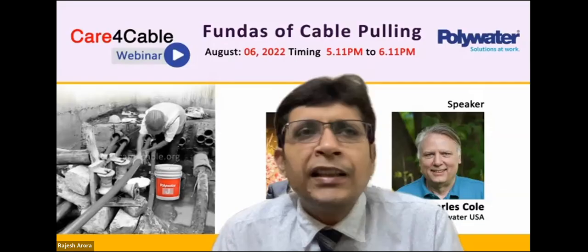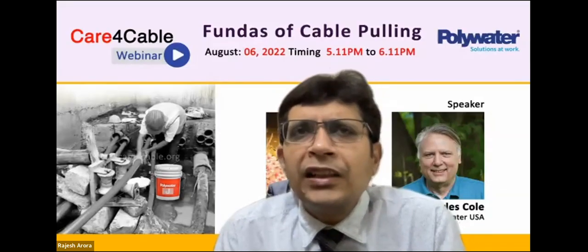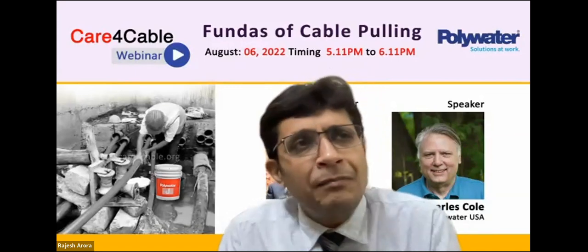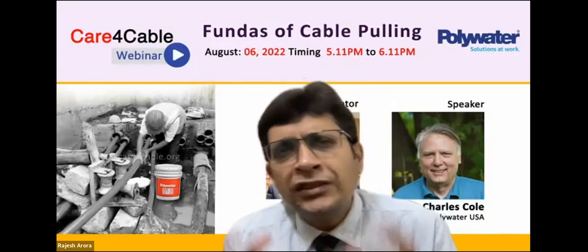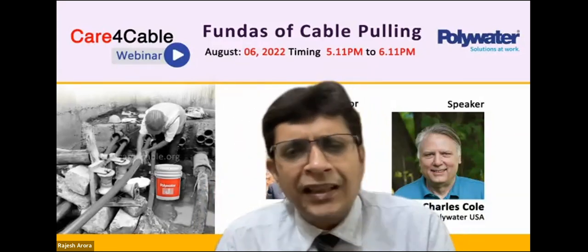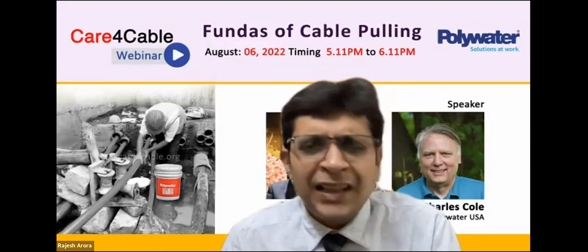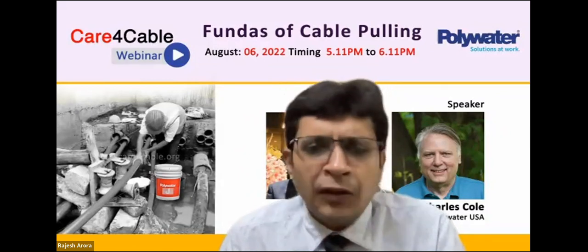Yes. I can suggest there are many good kits of meggers available that can pinpoint the fault. They use acoustic sensors. They move along the route of the cable, and with that acoustic sensor, they can pinpoint the particular place where the fault has happened. That is one of the ways. Yeah, we tried that. We tried with 3-4 different vendors with 3-4 different techniques, but no luck. So that is why we are stuck.